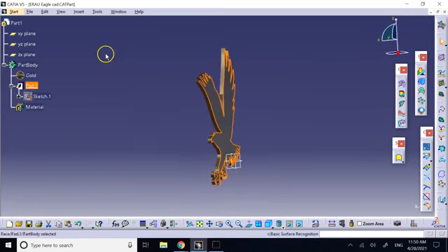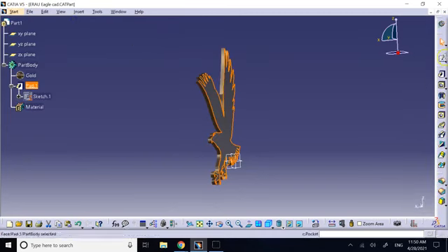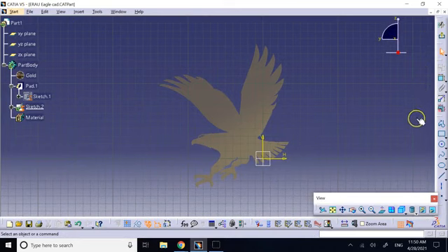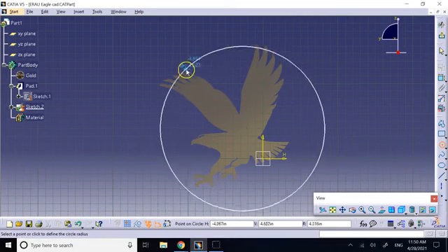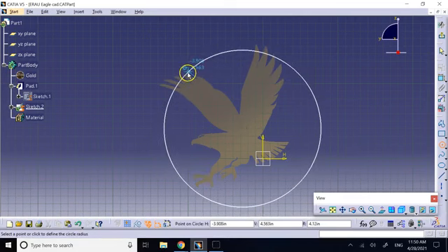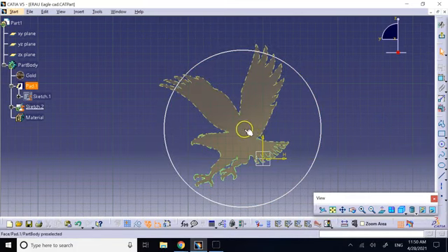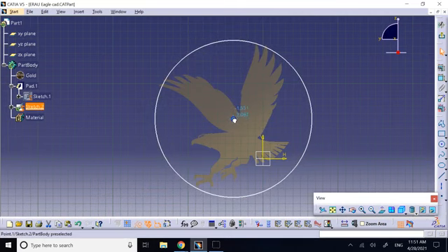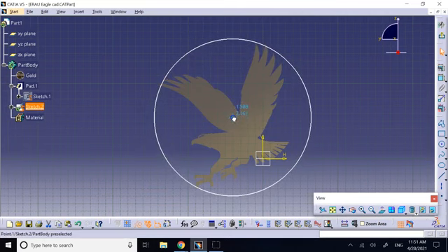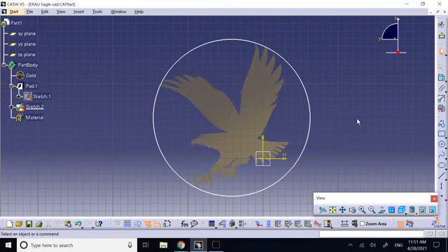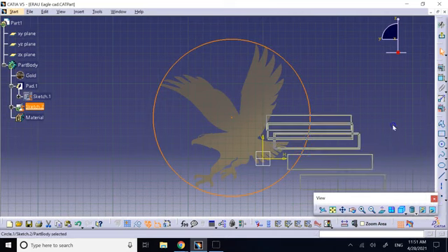So you just go to this surface, go back to part design, right? Select that surface, go to sketch, and draw an ellipse or a circle. If you can fit a circle, that's perfect. If you cannot, then maybe you want to go with an ellipse or something, as long as you can make it touch these areas, right? So maybe something like this is touching it all. And then if you want, you can create offsets from this guy, and let me show you an offset.